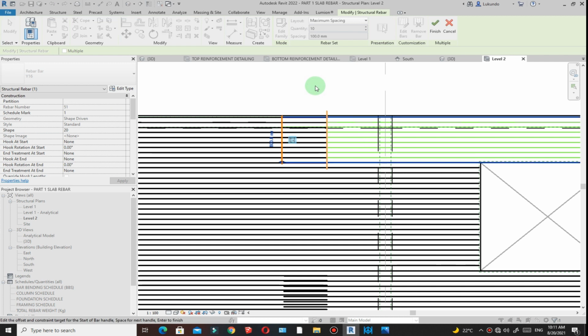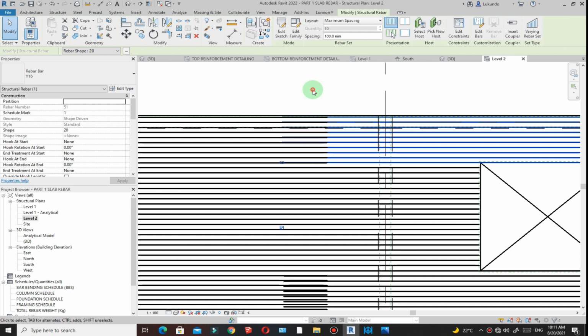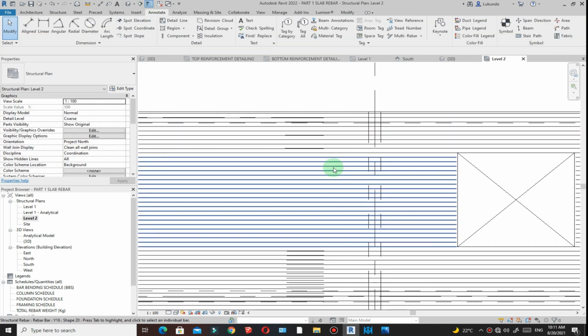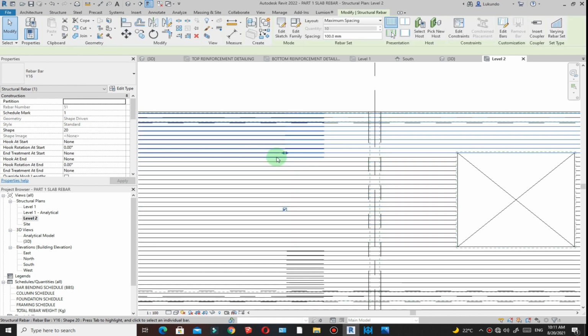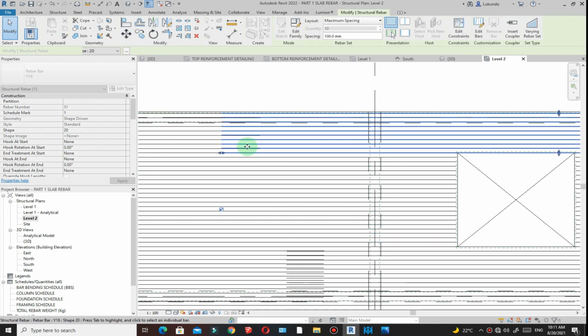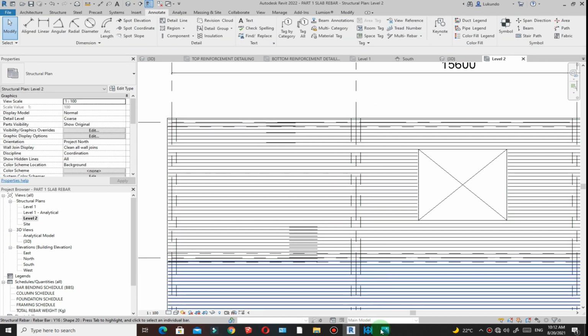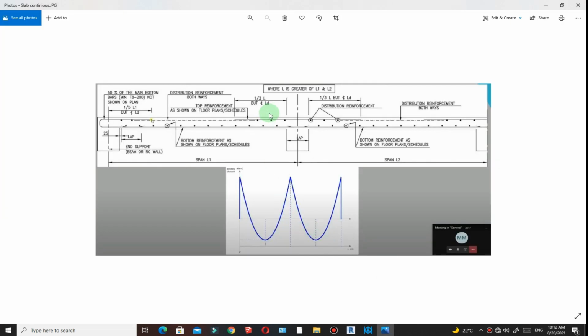Then click outside. As you can see, it adjusts, and then I'll click on finish. The goodness with the two-way constraints, if I just uncheck there, is that if I just select on the rebar and drag it, that lapping is going to be respected. It will not change. So it's just a matter of placing where you want the lapping to be, taking care of making sure that it's not within the maximum moments for your design.